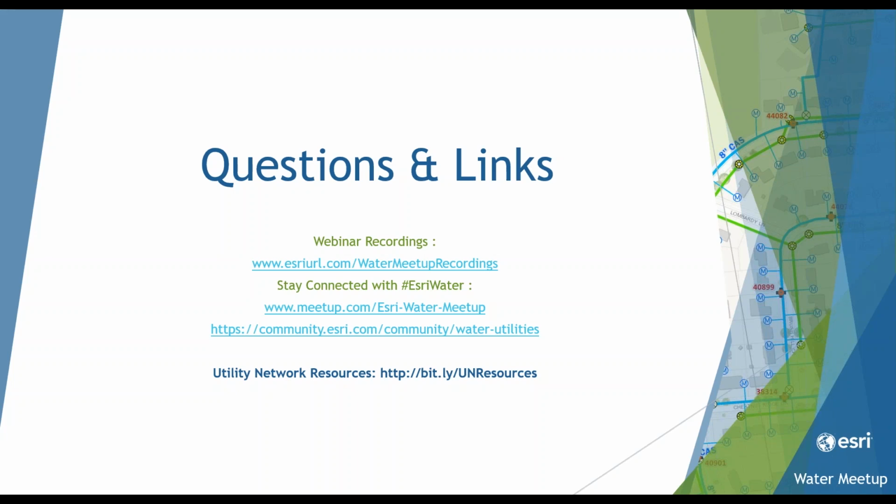Thanks, Jason. We also had several questions back to the licensing again. This is more specific to products. You were showing ArcGIS Pro. Is there a minimum licensing level you need for Pro in order to use the utility network? Yeah, so you need to have a standard level Pro license, kind of similar to what you needed with the geometric network with ArcMap. So you do need to have a standard level Pro license, and then again, you do need to have ArcGIS Enterprise.